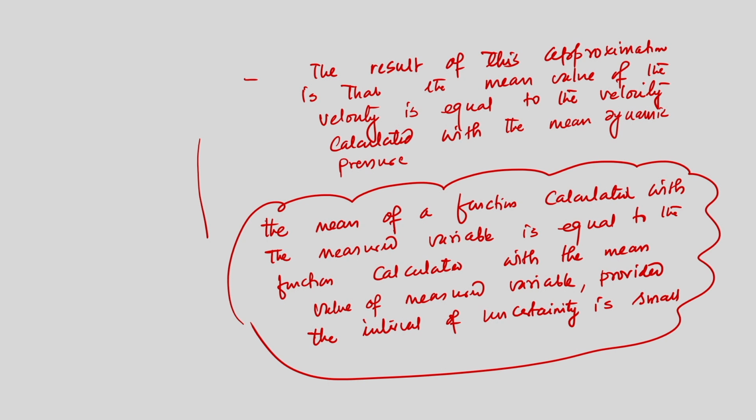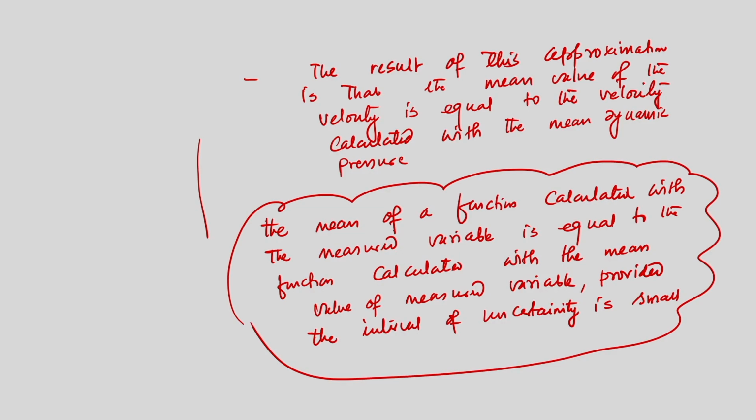And finally, we will work out one example. Today we have discussed different types of error, and we have seen that measurement errors can be classified into three different categories: blunders, fixed error and random error. Random error can never be eliminated, and blunders can be eliminated if we are careful in measuring data and when we are using any instrument to measure data. And the fixed error can be eliminated provided we consider the correction factor.